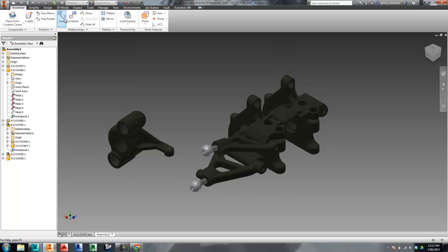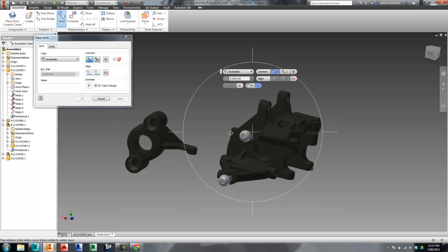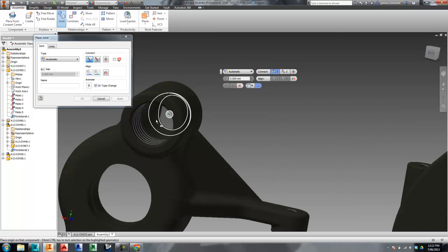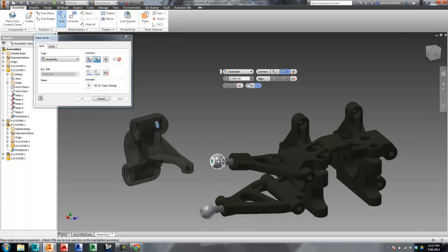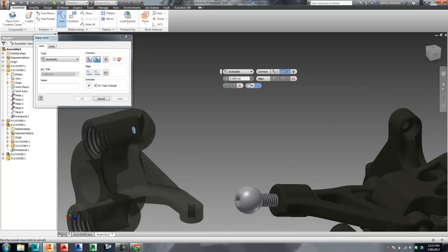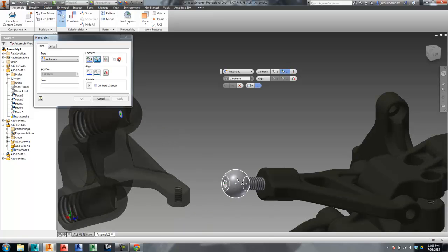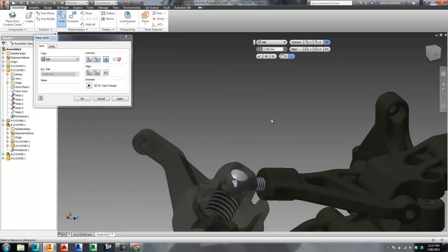Let's go ahead and use that joint constraint to build a ball and socket joint between this spherical object here and the internal spherical object here. So just select on that. You can see, by the way, when I'm doing this, depending on where I'm going to align it, that central area there, the central node of this sphere, is where I actually want to align the central node of this sphere. By hovering over it, I can see exactly where that alignment is going to happen based on that little green dot. Select on that, and that aligns the two together.